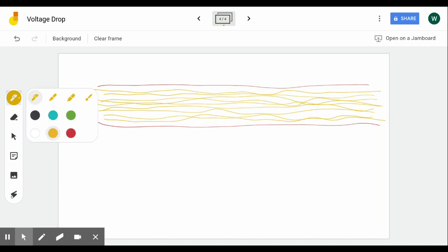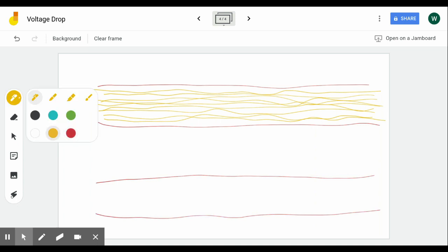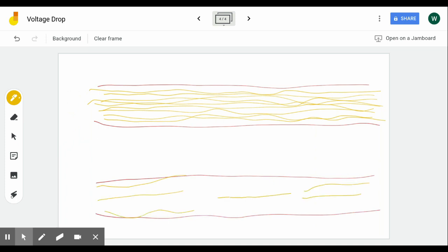Let's take, for example, a wire that is not healthy. Let's say that if we were to cut this wire apart, some of the strands are broken inside the wire. So now we have really just one strand through a portion of the wire that's making the connection. We've got corrosion in this wire, and the wire is deteriorated. So we still have an electrical connection through this wire, but we're down to just a couple of strands worth of connection.